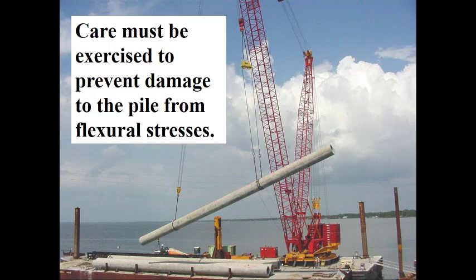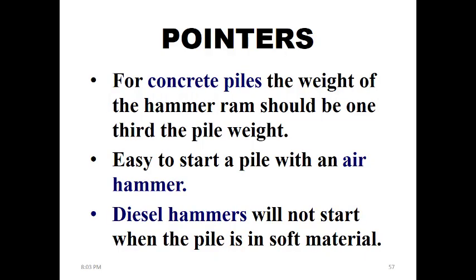So as a hint, pay attention to the moment diagrams, and it will give you an understanding of what can happen and why you have to pay attention to the location of loading the pile, even for a small movement in the construction site. So pay attention to the flexural stresses and you will see why it's important. Some pointers that will help in the process of planning.